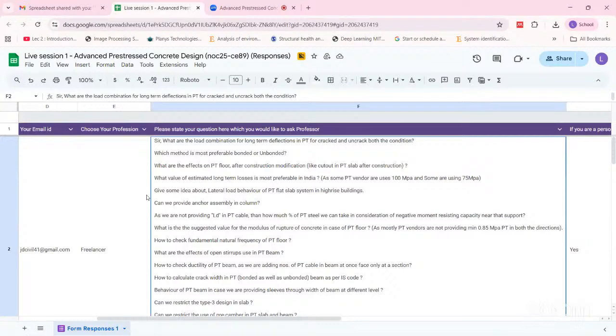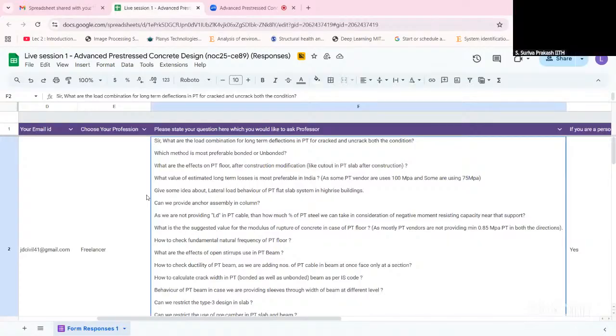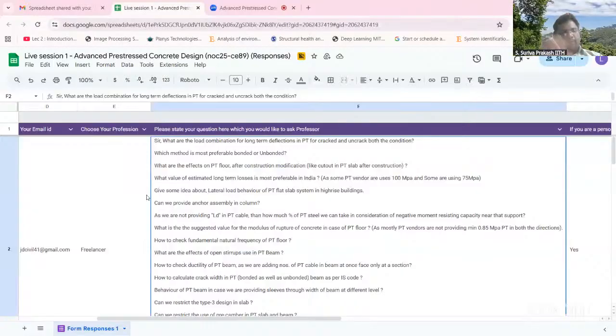If you have, let's say in precast, a ledger beam, right? They will usually be subjected to shear and torsion. Whenever you have torsion, it will have a spiral crack. So then you need to have these links on all four sides, right? Only then can it arrest the crack. So if your PT beam is going to have torsion, definitely U open stirrups are not acceptable, right?